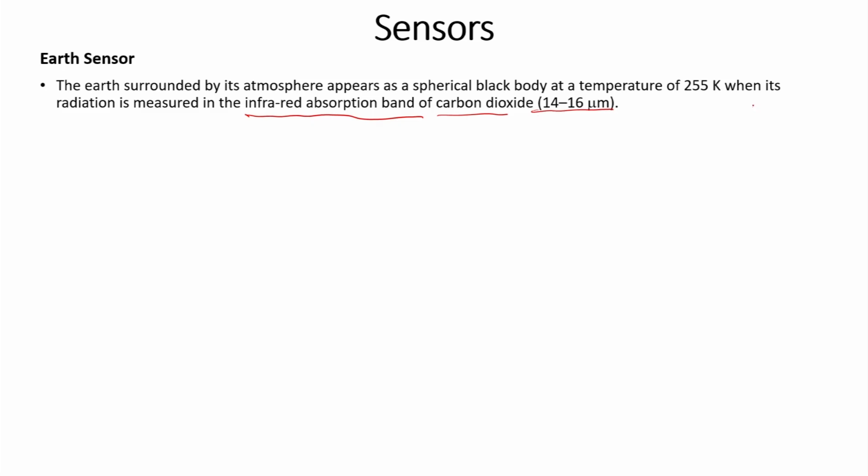Using different types of sensors, maybe 3 or 4, the center of the earth can be located, that is, its direction. The center of the earth means the yaw axis can be known using this earth sensor, but not just one, more than one are used. You can achieve an accuracy of 0.05 degree by using the earth sensors.